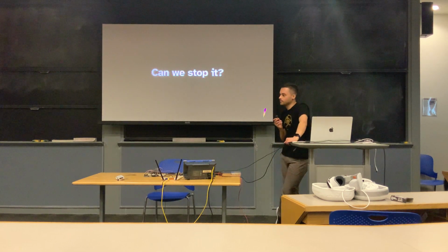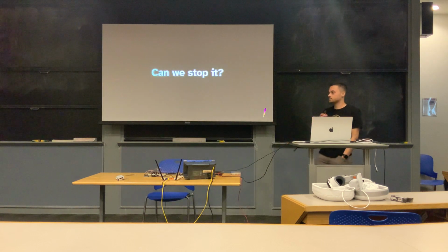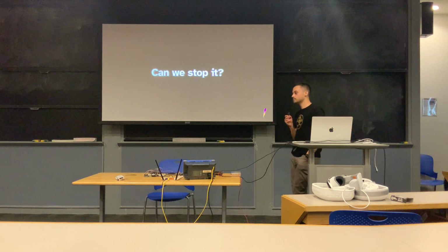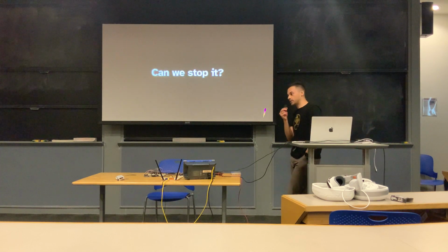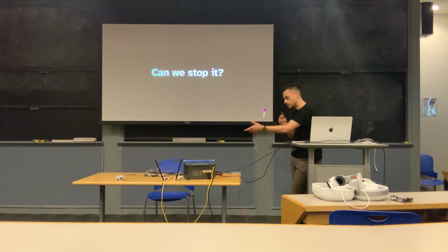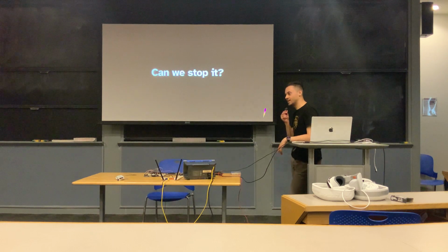Yes? I know there are built-in mechanisms that prevent clock skew in a lot of chips, but can that prevent this attack if not done well? Yeah, I'm not entirely familiar. It depends on the mitigation. There definitely are architectures out there designed to mitigate this. Atmega is not one of them. It's very easy to do this on an Atmega. More advanced chips might be harder.